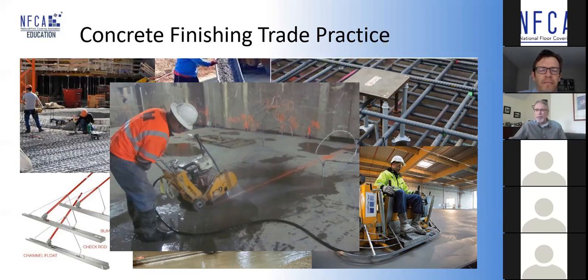But basically what we're looking at here is wet concrete finishing. They coordinate the supply. They look at quality testing at the point of discharge. They coordinate the subgrade preparation. They coordinate with formwork and reinforcing steel so that when they place the concrete, everything ends up in the right location. They put in place all of the embeds, the plates and the pre-manufactured expansion joints. They coordinate placement of mechanical and electrical services, particularly those things that have to be at the same level as floor coverings.